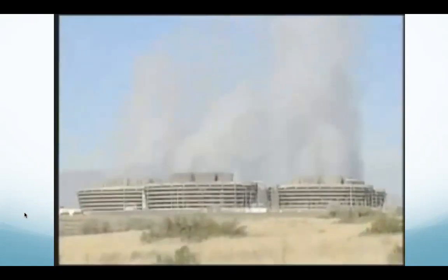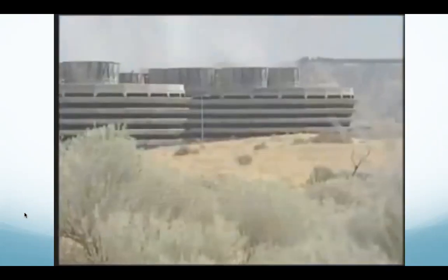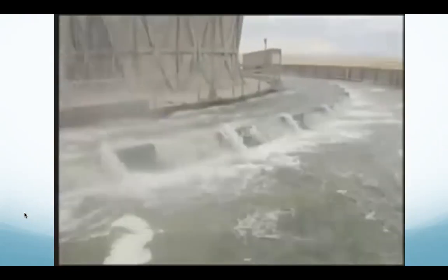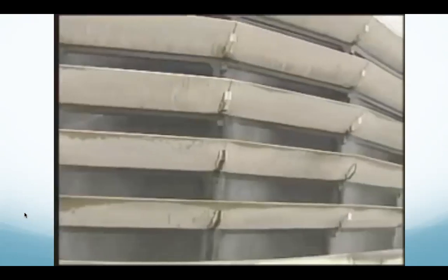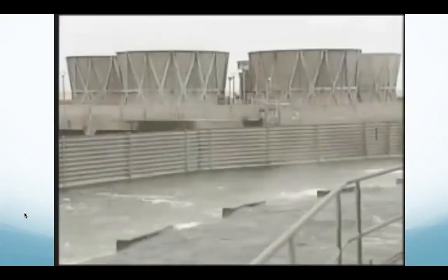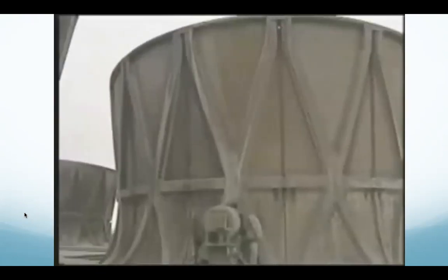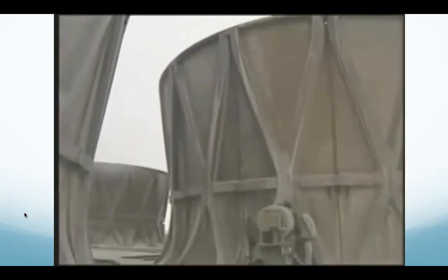The water inside the pipes absorbs a lot of heat, so we have 6 large cooling towers to remove this extra heat. Hot water from the condenser pipes is pumped into large canals at the top of each tower. From here, the water is allowed to fall down across special inserts called cooling tower fill. Large fans pull air across the water, causing the heat to evaporate into the atmosphere. At the bottom of the towers, the cool water is collected and pumped back to the condenser to be used again.